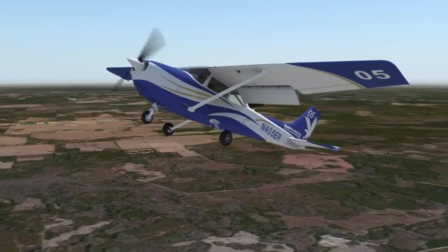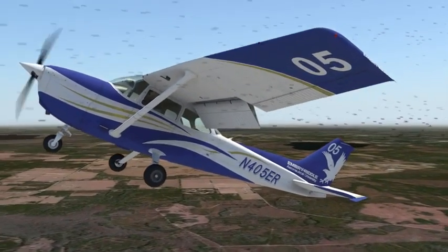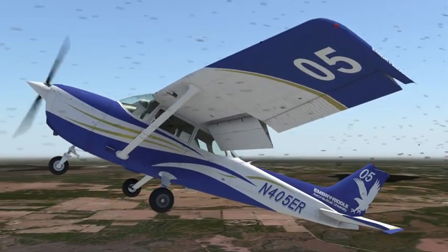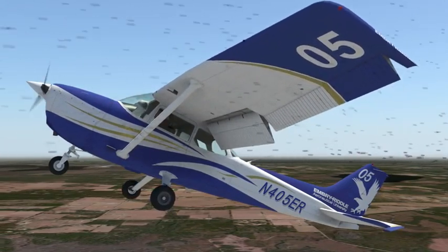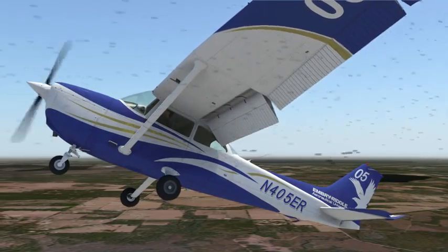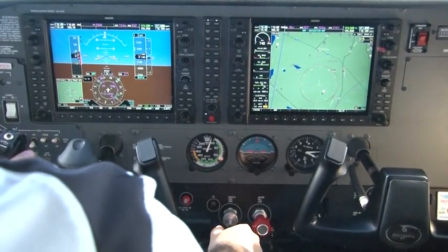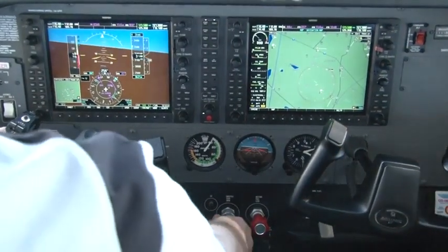One other thing to keep in mind at slow airspeeds is that there is much less airflow traveling over the flight control surfaces. As such, any input you make on the flight controls will not have the fast response one would be used to. The flight controls will feel mushy and may require large inputs before any real response is felt.